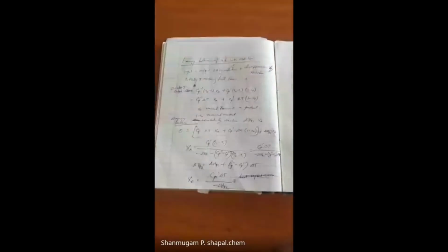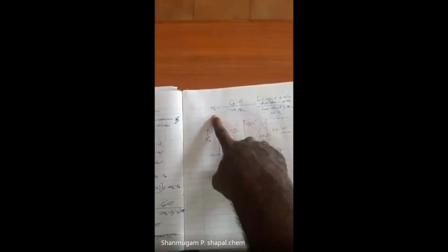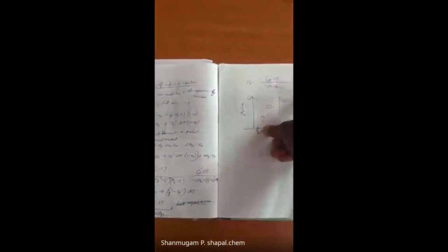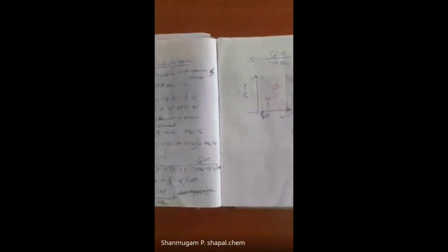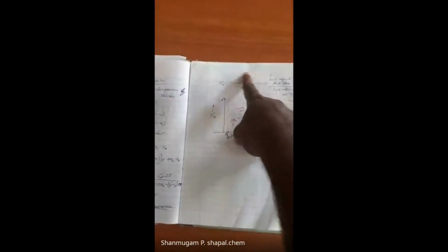So you sum this up, and here the system is actually closed. In a closed system, we don't have any input in the system. Once you derive all this, we will get a relation between conversion versus temperature, with respect to the specific heat of the system. So this is the heat required to raise the feed stream to a particular temperature, relative to the heat released by the reaction. That was the ratio here.